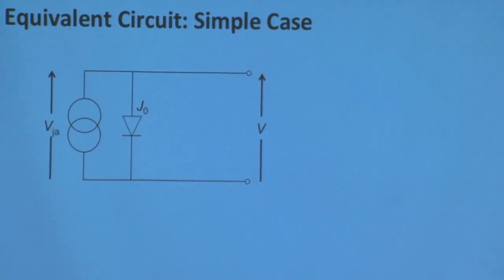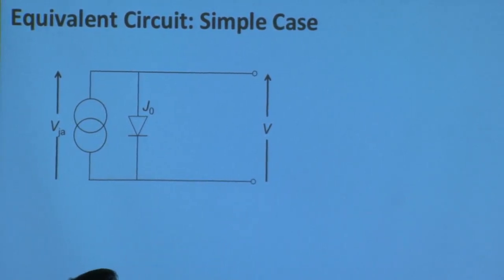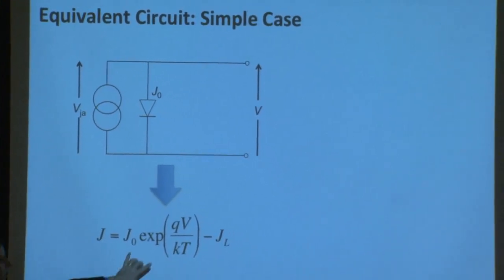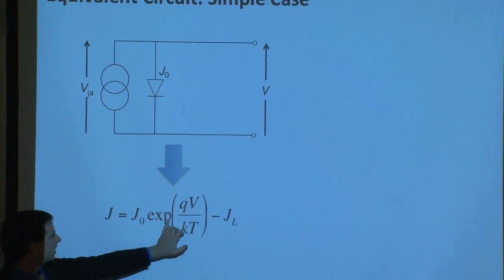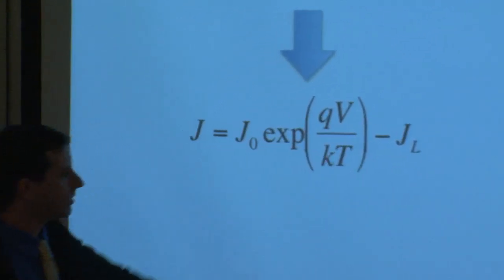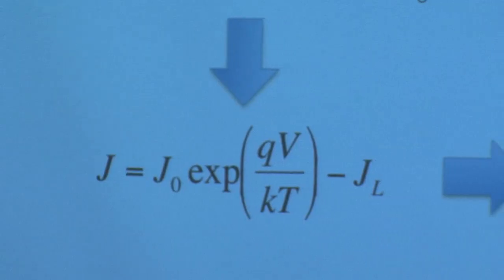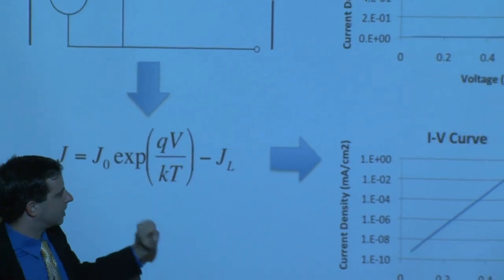So we have this voltage and current being generated by the solar cell, and that would be described by the ideal diode equation. My apologies, there should actually be an exponential of this minus 1 right there. We should take note of that and correct it. I just happened to notice that. OK, so the ideal diode equation is right here.